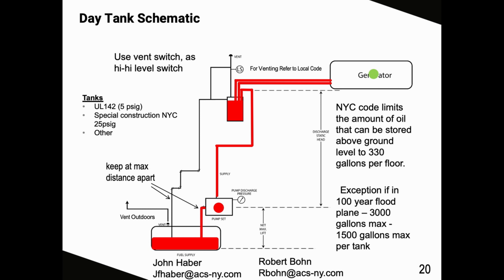So that's how you decide whether you're going with the UL 142, or, if New York City, you need New York City approved. New York City, that's correct. And that applies for day tanks or main tanks? Either one. You're going to have the same effect on the vent line for either tank.